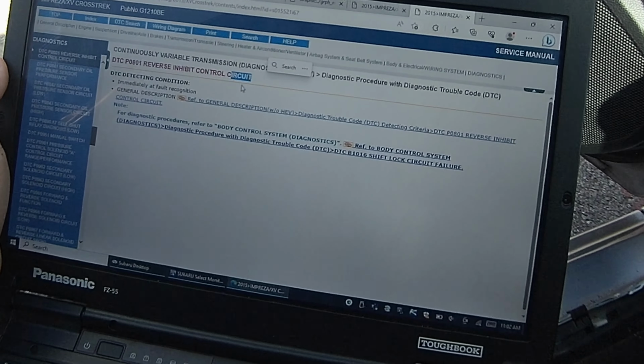Judge as an NG, a no-go, if abnormal signal from the integrated unit is received, when bus off is not detected, and there is no trouble in CAN between the integrated unit. So that means we're also looking at a CAN signal. Okay, enabling conditions, secondary parameters, malfunctions listed on the right column are not detected. Okay, those are network codes.